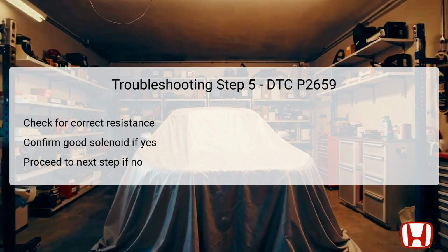If the resistance is outside of this range, that raises a flag that the solenoid may be defective and requires replacement. Following these steps methodically helps ensure that the technician makes informed decisions about potential repairs. Accurate documentation of the findings is critical for understanding the nature of the malfunction.